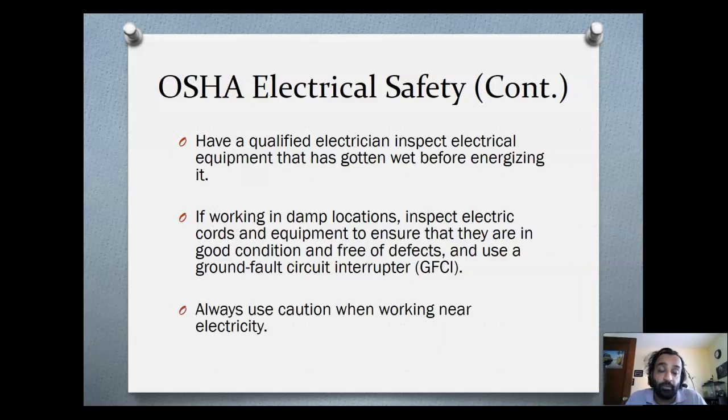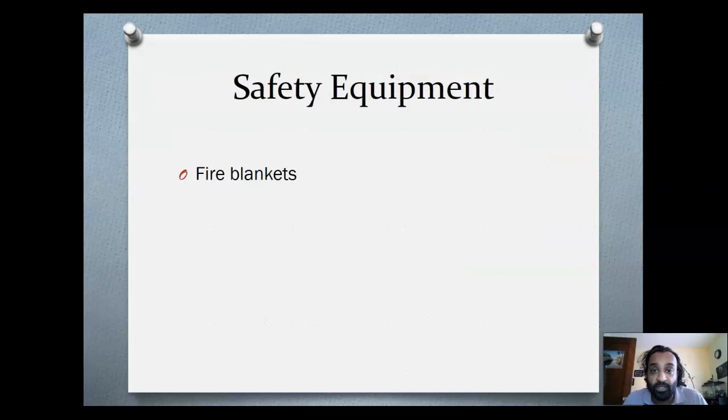Do not assume again that the system is not live or dead. It could be alive and you don't know. So when you lean or you have something behind you, make sure you're not leaning or touching against wires that you're not sure if they're dead or not.